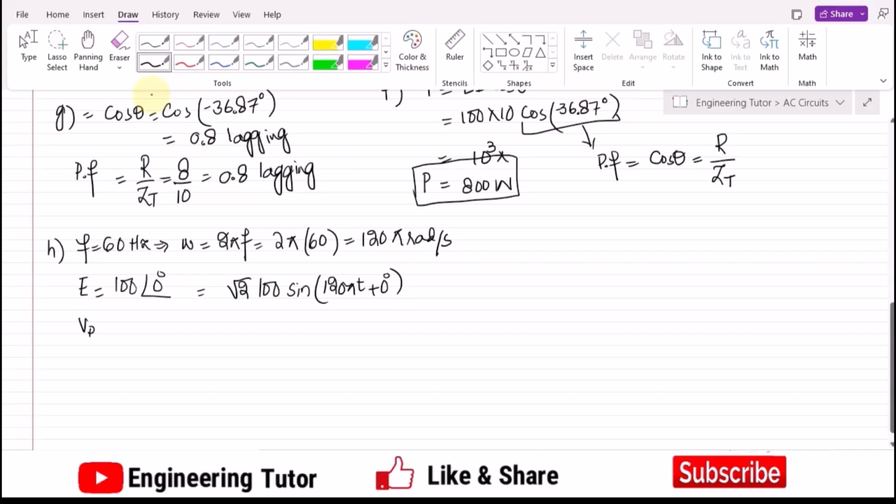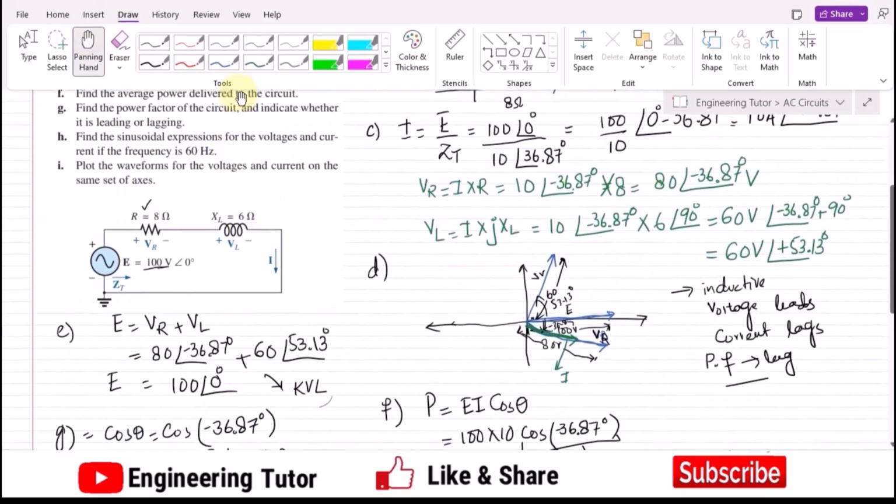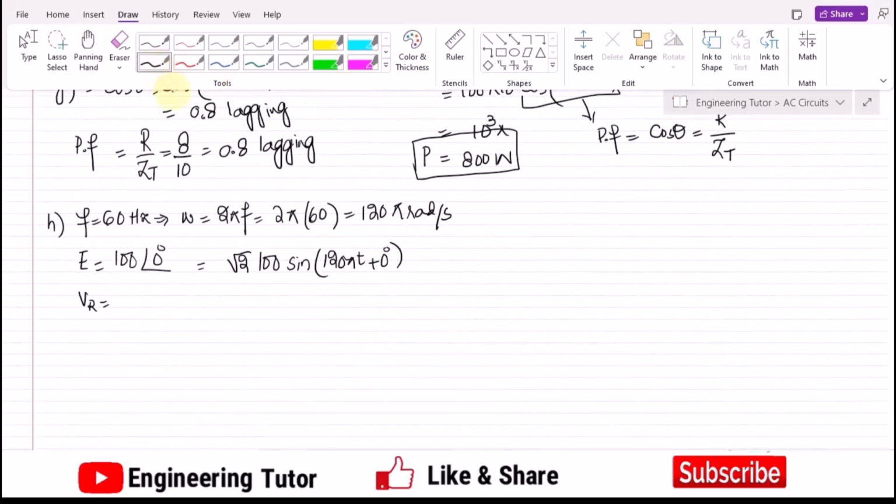Similarly, the value of V of R was how much? The value of V of R was 80 at minus 36.87. So the same procedure here, the same rule here, square root of 2 multiplied by 80 and sine of 120 pi t, and the angle it has is minus 36.87 degrees.